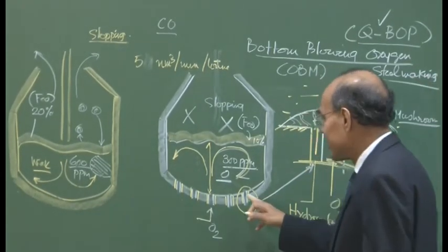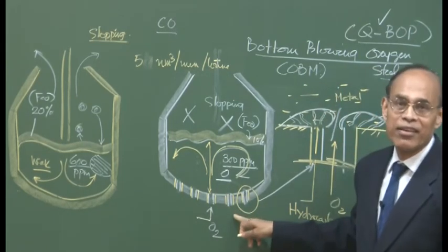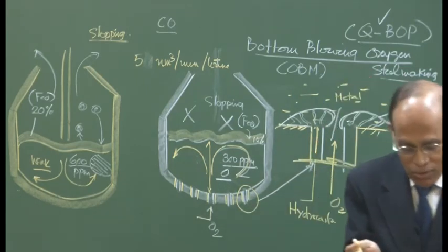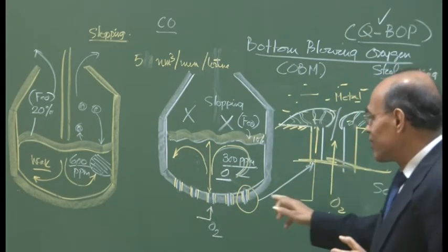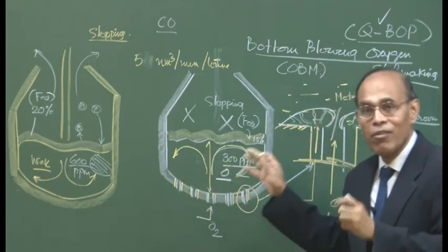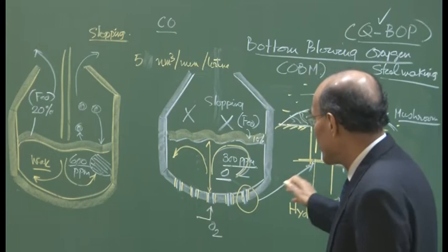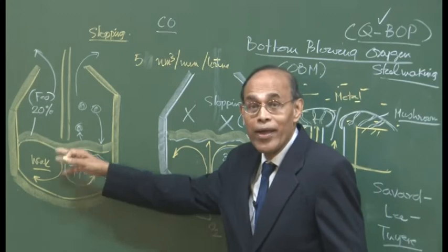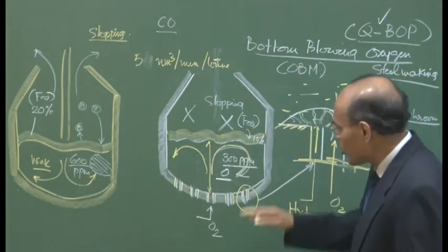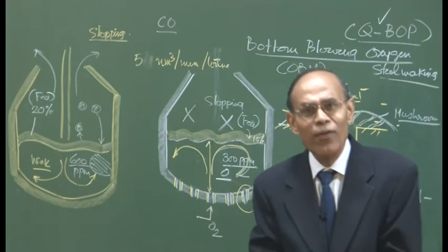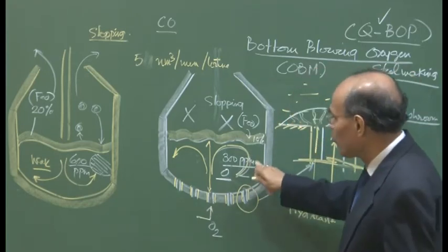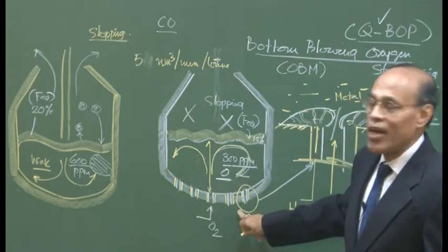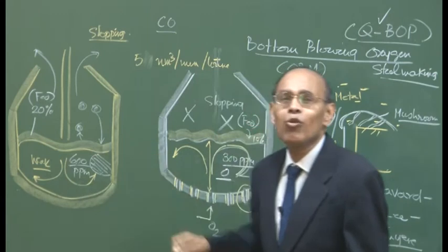Because the maintenance of the bottom refractory wear is still a problem. Although one could solve the problem, it requires vessel turn down time; relining becomes quite frequent in comparison to a top blown vessel, where there is no such refractory replacement. So the bottom needs to be replaced much more frequently, or the bottom blowing steel making process requires more intense maintenance of the converter lining on the bottom than the top blown converter.